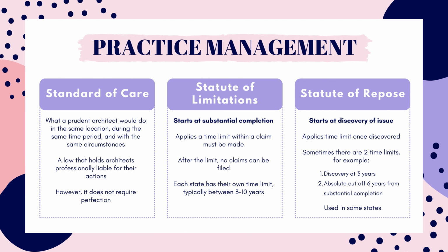Standard of care is what a prudent architect would do in the same location during the same time period and under the same circumstances. It holds the architect accountable for their professional actions, but it does not require perfection. Statute of limitations begins at substantial completion, and it sets a time limit for when a claim can be filed. After that time, no claims can be made. Each state has their own time period, but it's typically between 3 and 10 years.